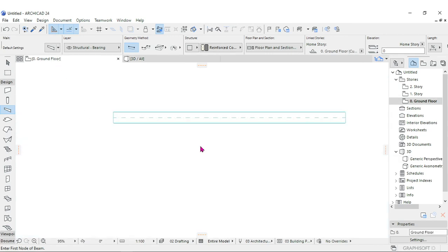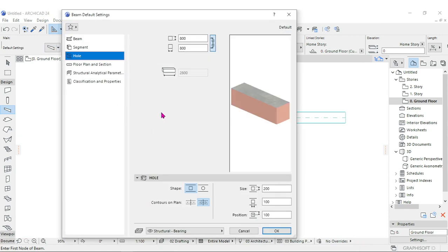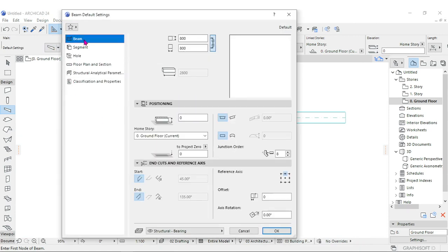Now this column, you can decide to modify it, or even I'm going to click another one, but this one, I'll proceed back to the beam. We'll have it slanted. So in case you want a column that is slanted to an angle, let's say 45 degrees, your column will be slanted at an angle of 45 degrees. And it is very similar to the column. So if you want it slanted, you choose an angle there. I'm just going to proceed with this one.